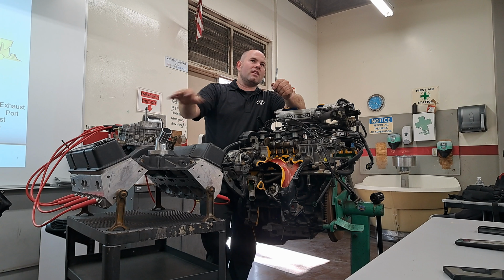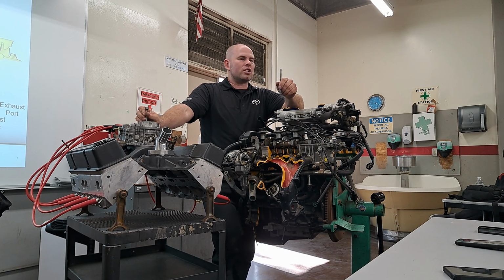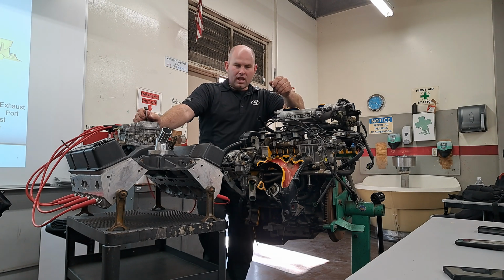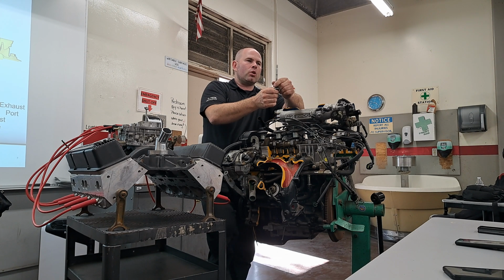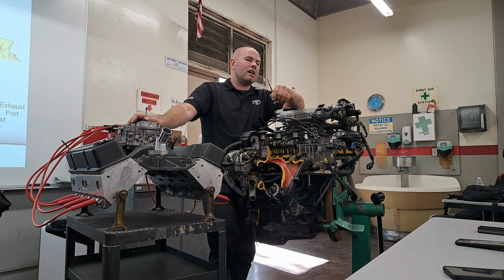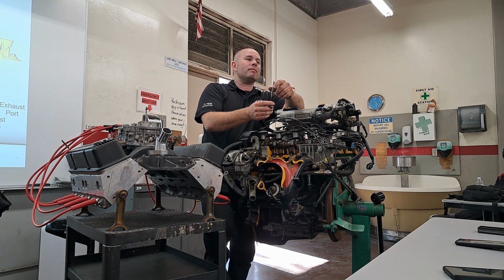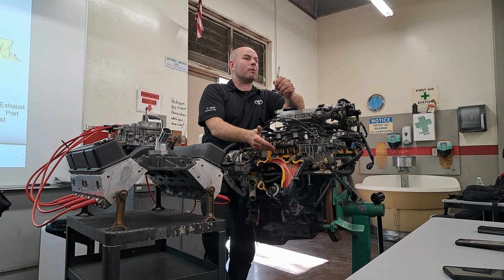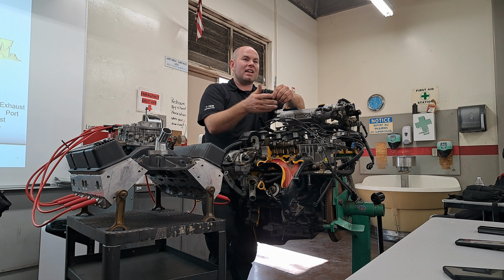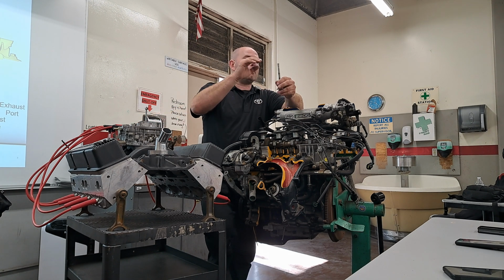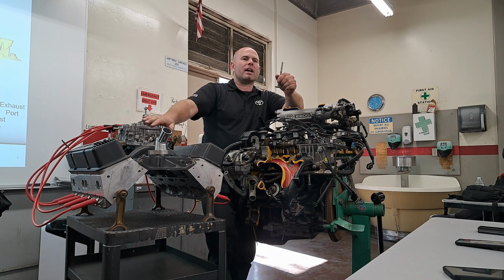Closing the valve is a little sketchy, like at high RPMs. Something I always think of is, have you ever heard the term valve float? That's when your cam pushes it open directly, but then you're relying on the spring to pull it closed. So when you're turning 18,000 RPMs like we talked about earlier, that valve's like, yeah, I'm coming, but that piston's like, I'm coming right now. I'm gonna catch up to you. And they can, if you're at high enough RPM and your valve is a little sloppy and floats a little bit, it can actually catch up and smack it. So that would be like true valve float.